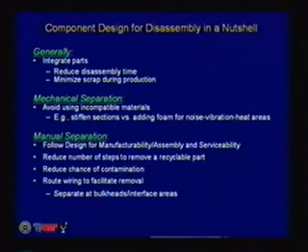In general, don't mix materials. Foams make a difference, especially if you're going to be mechanically separating through a shredder. Manual separation: it turns out that if you follow the guidelines for design for assembly, you're probably going to have a design for disassembly that's pretty good. You can certainly cook up cases where that's not the case, but in general, follow the design for assembly guidelines. We'll go through some of those in just a second.